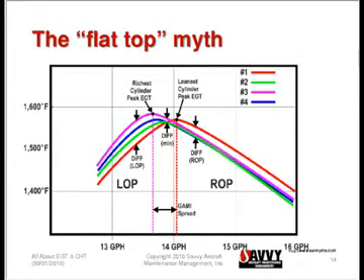And if we richen the mixture to a reasonable rich at peak setting, or especially if we lean it to a reasonable lean at peak setting, the difference gets much larger. The notion that we want to minimize this is totally wrong, because if we try to minimize it, we're operating right where we don't want to be. And again, I'll make that clear in a later slide. What we really care about is not this difference between the highest and lowest EGTs, which really doesn't mean anything.